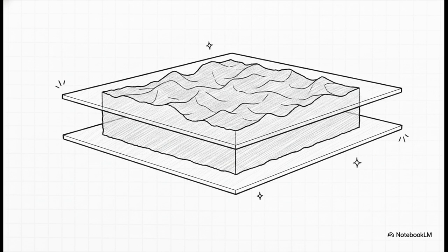The standard even notes that flatness can be applied on a unit basis. That means you can specify that a surface must remain extremely flat within a small specific area, say like a 25 by 25 millimeter square, which limits those abrupt surface variations across a much larger plate.